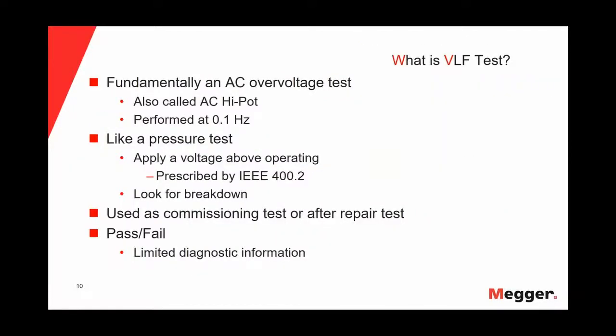What is the VLF test? Let's start talking about the VLF test. The VLF test is fundamentally an AC over voltage test. It's also called AC hypot. And the frequency we use for this AC over voltage test is 0.1 Hertz.